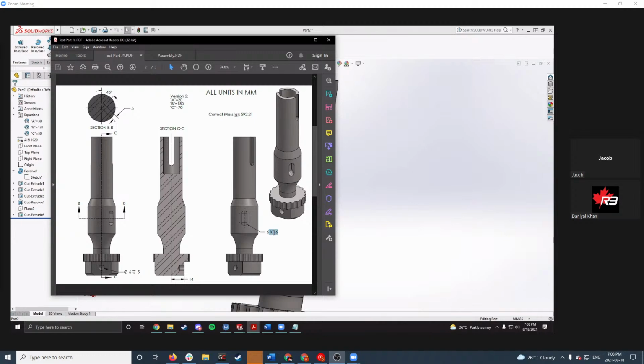If I'm to 6 by 16, this is referring to the width of the slot and the length of the slot. So the 16 is referenced from the center point of the top circle to the bottom circle, which is where you would measure your length from for a slot.